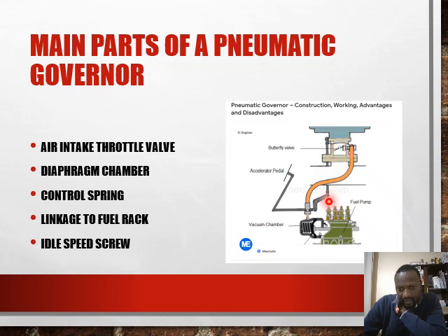And then we have the second unit, which is called the diaphragm unit, which is attached to the rear of the inline injector pump and has a push rod attached to a diaphragm that actuates the pump rack. So it's good to note that this engine does not have a mechanical connection to the injector pump. Rather, the accelerator pedal operates the throttle valve. As you can see, this linkage here, the pedal is linked directly to the throttle valve, just like a petrol engine.